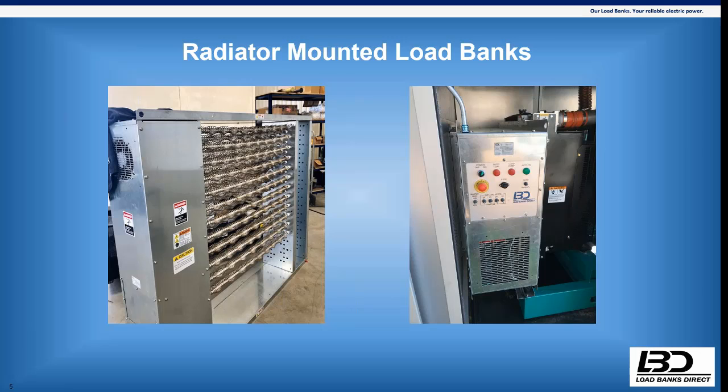With the radiator mounted load bank, the packager can put it in the housing. They can have a separate breaker that feeds the load bank. And the hardware cost alone for a 500 kW duct mounted load bank might be half the cost. It'll be less than half the cost of that. It'll be like $8,000 to $9,000. So it's a very cost-effective solution.